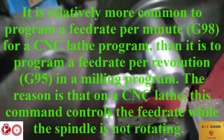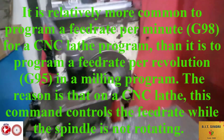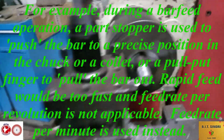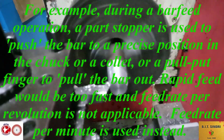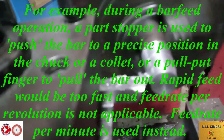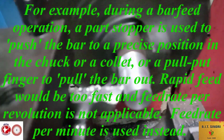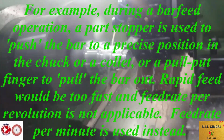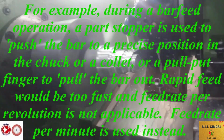The reason is that on a CNC lathe, this command controls the feed rate while the spindle is not rotating. For example, during a bar feed operation, a part stopper is used to push the bar to a precise position in the chuck or a collet, or a pull-out finger to pull the bar out. Rapid feed would be too fast and feed rate per revolution is not applicable. Feed rate per minute is used instead. In cases like this, the G98 and G99 commands are required in the lathe program. Both commands are modal and one cancels the other.